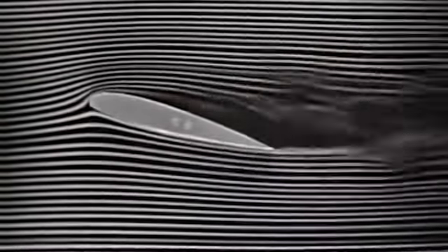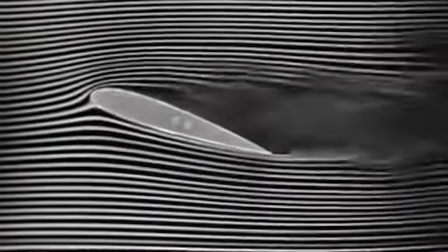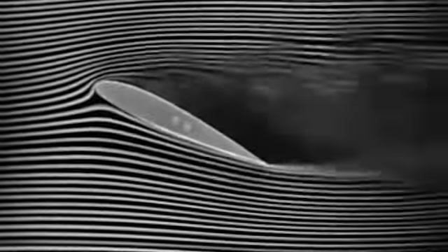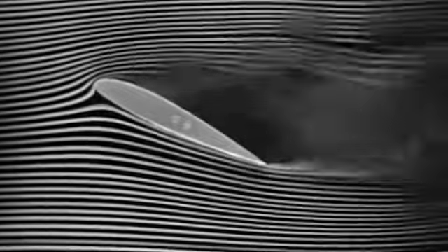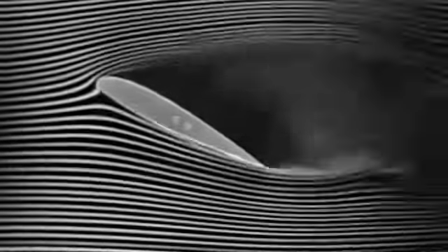But that weird thing makes some sense, because if you visualize a circulation of air here and you superimpose on that a translational motion of air, the combined effect is a flow like you see over a wing. And so the lift depended on the circulation. So it still had to be calculated, and that was a major challenge. The next 30 or 40 years, it was something called the circulation theory of lift.